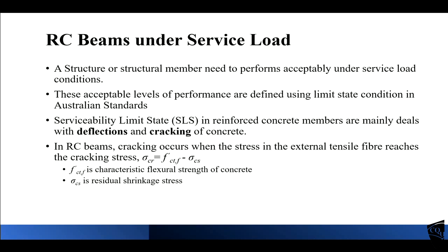So if you remember, as undergraduates, sometimes you might do the beam test we talked about last week. Flexural strength of the concrete, we use the beam. When you apply the 4-point loading, the concrete will crack or fail. That gives our flexural strength of the concrete, f'ctf. So that is the flexural capacity of the plain concrete.